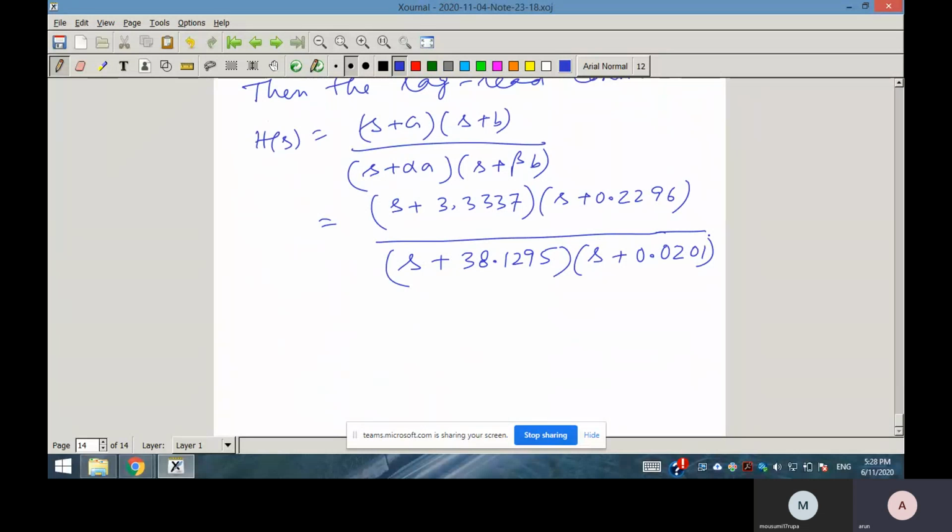Okay. So you can see that the lag controller is acting like almost a pure integrator, a PI type of controller here. Because the lag controller's main objective here is to provide phase attenuation, and the phase lag that is provided by the lag controller is assumed to be negligible. There's only 2 dB here.